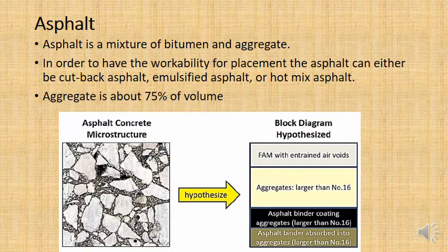The other thing is you've got to make sure that the aggregate particles in the asphalt are reasonably well graded. If they're not well graded, then you're not going to have workability.